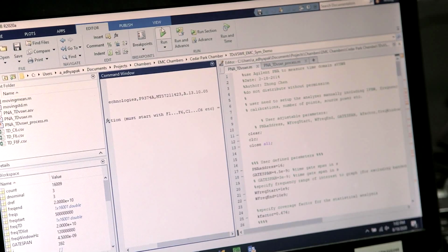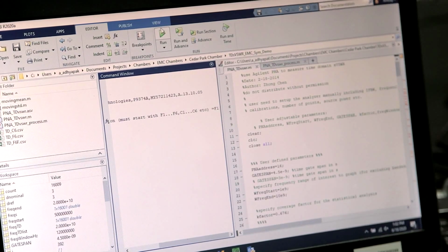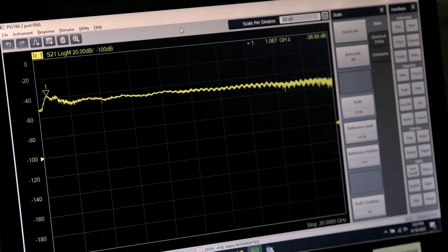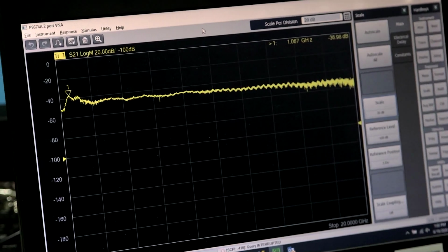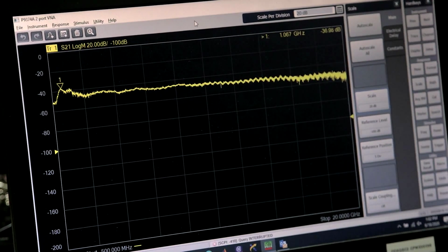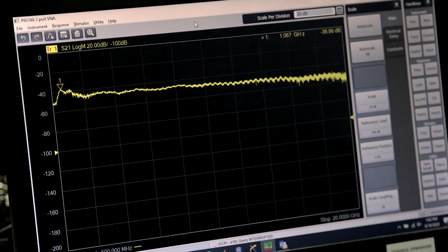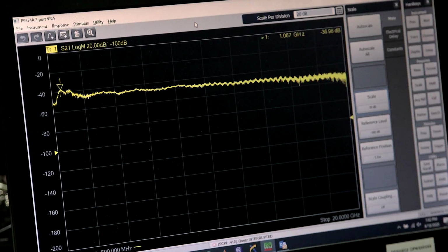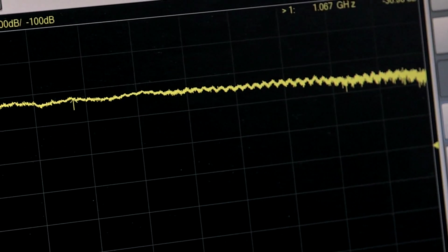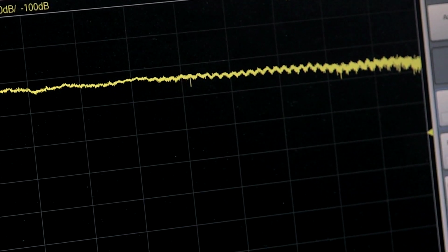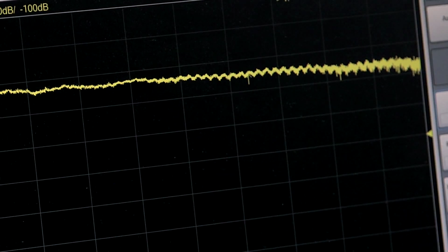As you can see from the screen, it basically took only 10 seconds to conduct this test for one position. If we compare this technique to our conventional CISPR 16-1-4 method, we had to do 6 locations at every position, and each location would be about the same amount of 10 seconds of sweep time. So we basically reduced our test time from 6 positions to only 1 position using this method.